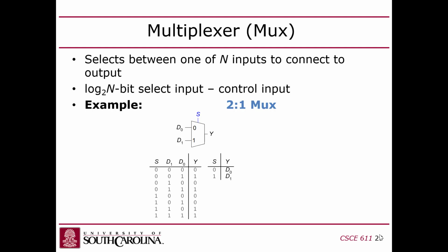So this is essentially a hardware if statement. That is what a multiplexer is, a hardware version of if in a programming language. As you might imagine, they come up a lot, because anytime you have any kind of conditional behavior, you have a mux in there, right? Make sense?